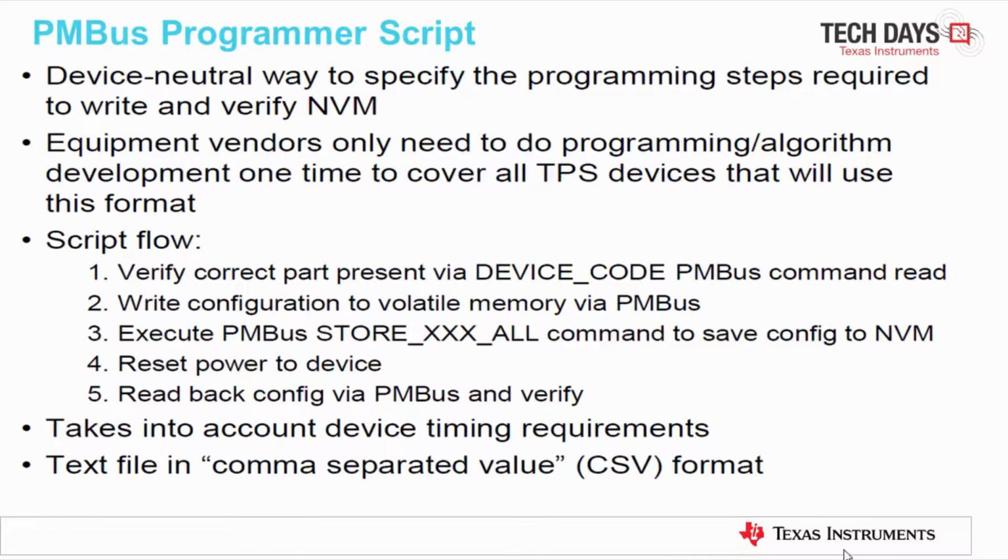The PMBus programmer script is very easy. It's a device-neutral way to specify the programming steps required to write and verify the values in the IC NVM, non-volatile memory. Equipment vendors only need to do programming algorithm development one time to cover all TPS devices that will use this format. The script flow goes like this.